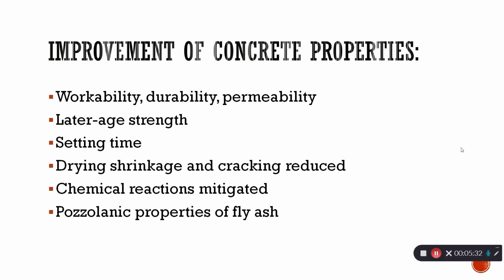The setting time of concrete is delayed when using fly ash, and this can be a beneficial application. Drying shrinkage and cracking can be reduced, and the harmful effects of alkali-silica reaction can be mitigated with the use of fly ash. Workability is improved when fly ash is used as a replacement in concrete mixtures because of the spherical particles that reduce friction and require less water.